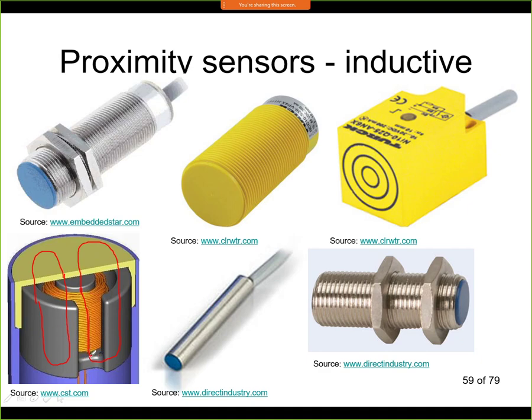Here the magnetic flux goes in the core, but here it has to go through the air, and it's protruding into the free space, and when we approach the object, it will distort the magnetic field, change the properties of the inductor, and we will be able to detect this.